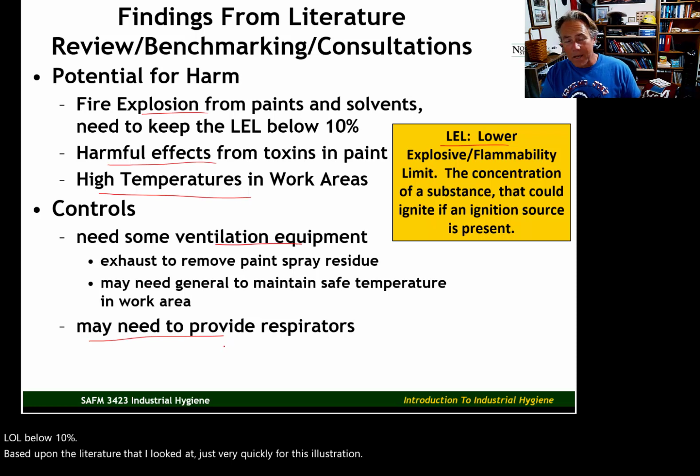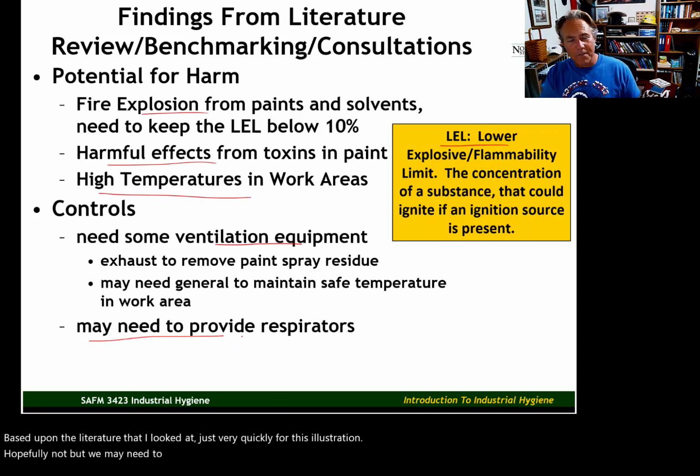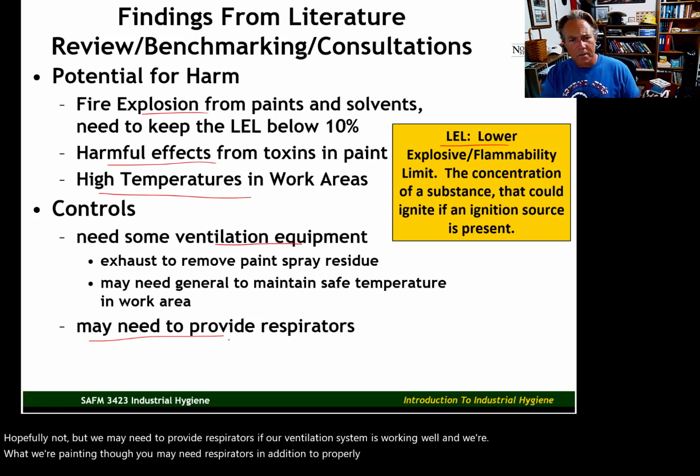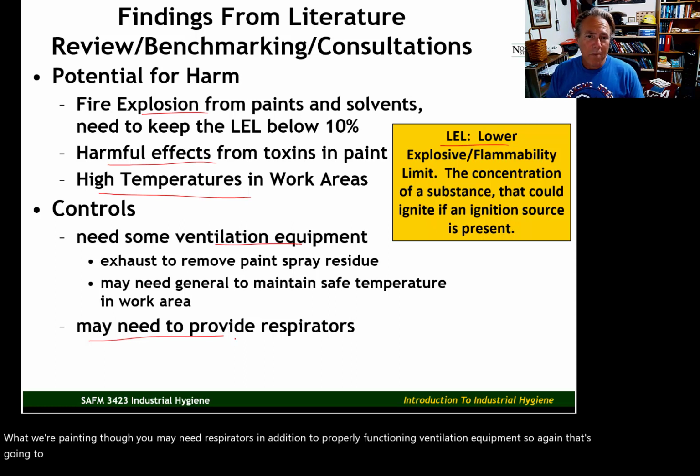Hopefully not, but we may need to provide respirators. If our ventilation system is working well, with painting though, you may need respirators in addition to properly functioning ventilation equipment. So again, that's going to be based upon the exposure level, the concentrations in the work areas.